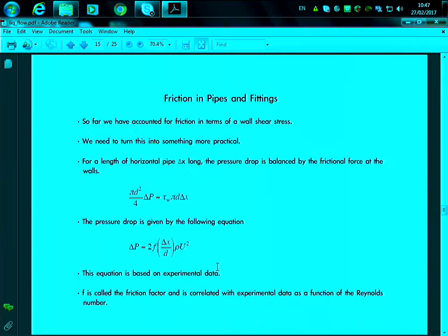So here you can see the Reynolds number and the friction factor, how it is related. For a laminar flow, it's a very straight line, very easy, but for turbulent flow, what do we have to take into account? The roughness of the pipeline, the relative roughness, okay? And the relative roughness will be the roughness over the diameter. So you take the relative roughness and the Reynolds number, and then obtain the friction factor from the chart, input that into the equation, and then take the pressure changes due to the friction of the fluid.